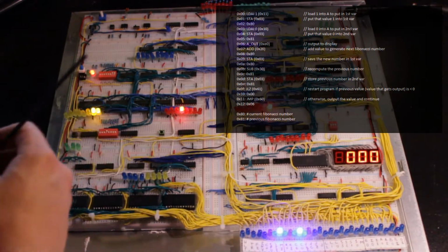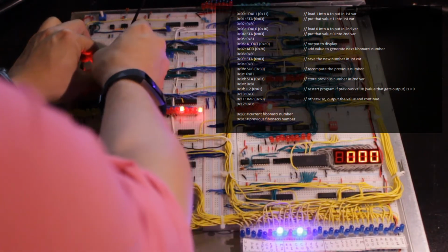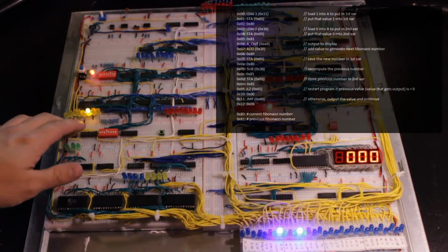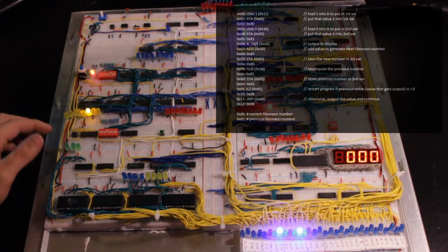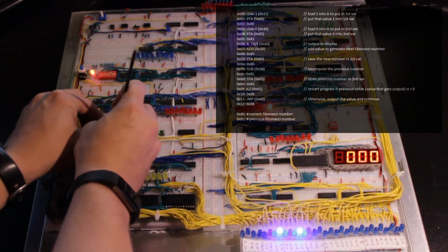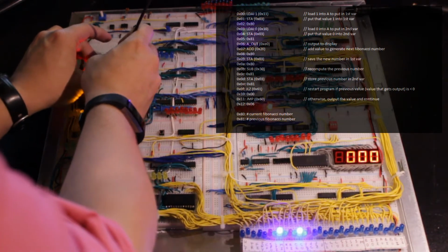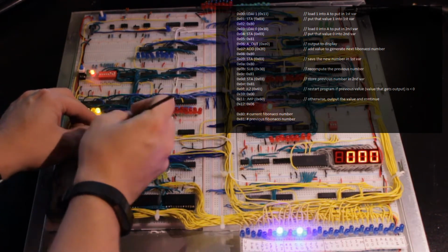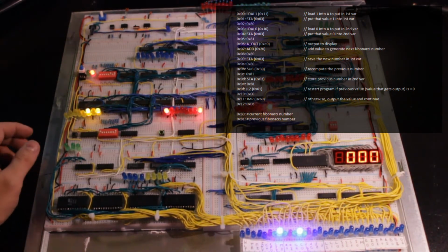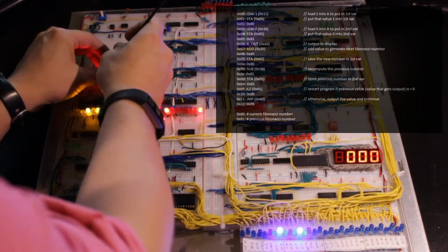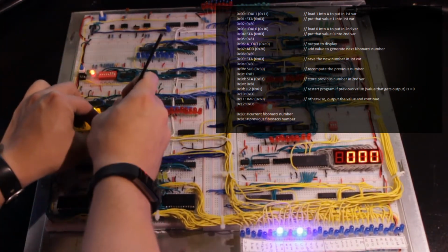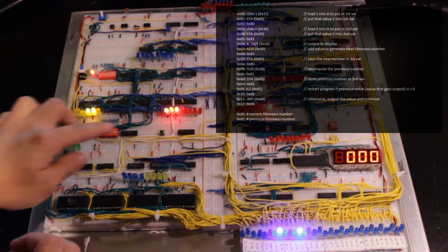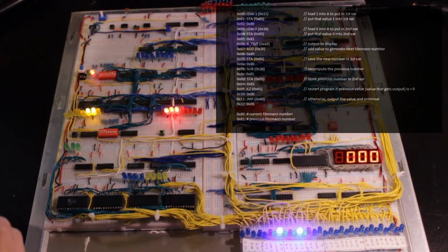And then the next instruction, we're going to be storing that value in another random memory location I'm using for a variable. I'm going to use hex 81, so we're going to put a store A command, which is a hex 03, and then in the next index, memory index 5, we're looking to put where it's going to go, which I just said would be hex address 81. And then after that, in memory index 6, we're going to put our output command, our output A register command specifically, which is hex E0. So I put in an E there, the first 4 bits, and a 0 in the second 4.